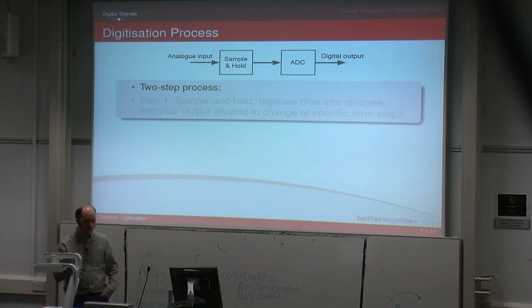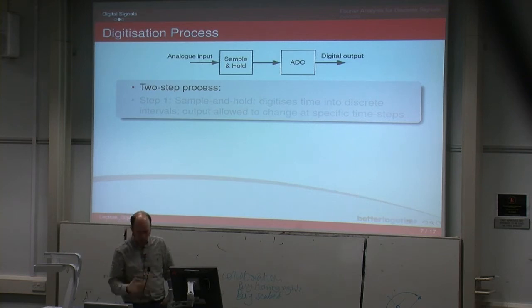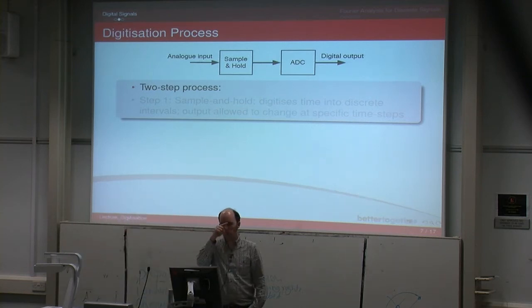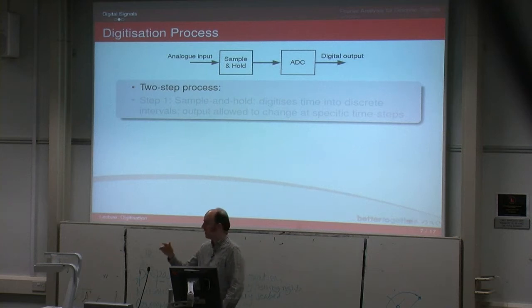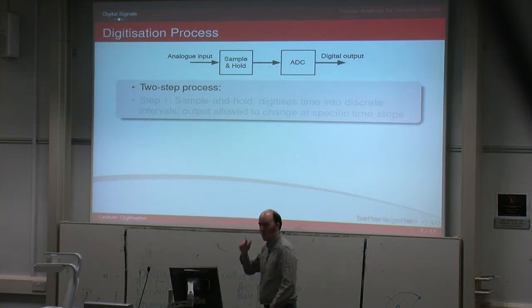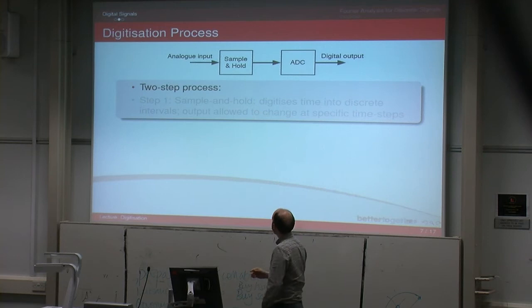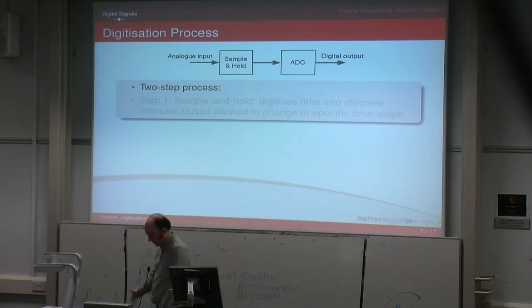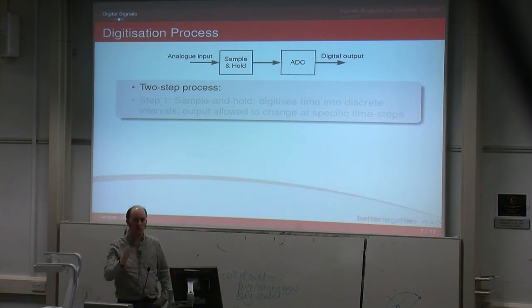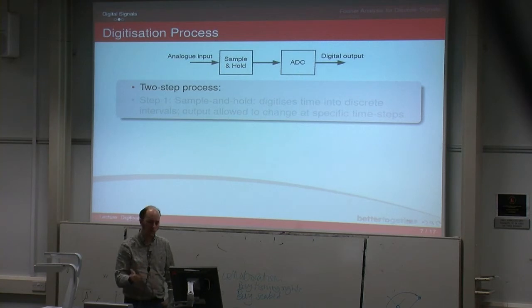Depending on the design of the filter, and that's the electronics behind it, you can reduce the amplitude or completely eliminate the amplitude of any frequencies above a certain cutoff frequency. So, say your ADC is working at 150 hertz, you'll set the filter so it cuts off all frequencies above, say, 75 hertz or whatever.